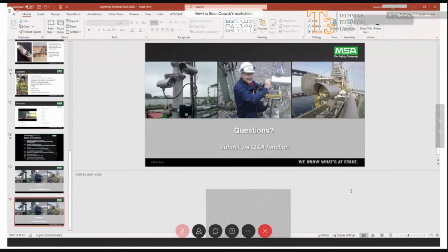So the next question was, does this support HART communication? Yes, it does have HART communication, but I believe you still need the site software in order to commission the unit, because you have to connect them with the site software. You have to connect the transmitter and the receiver, and then do your alignment check. And it tells you what kind of signal strength is there, and if it's ready to go, it'll be deployed.